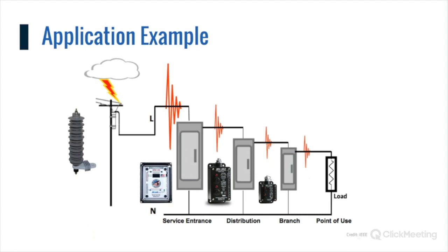And remember what we said, 80% of the transients happen within your own facility, at the point of use, not back up here at the utility. So if you have all your protections just here, then you're not protecting any of this equipment, or the equipment that's attached to the same panel, from transients that are created in your own facility.